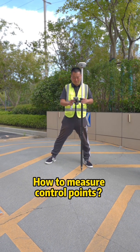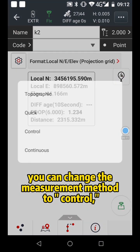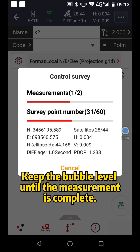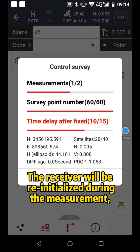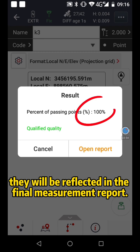How to measure control points. If you want to measure points with higher accuracy, you can change the measurement method to control, move to the point, tap measure button, keep the bubble level until the measurement is complete. The receiver will be reinitialized during the measurement, so if there are errors caused by interference, they will be reflected in the final measurement report.